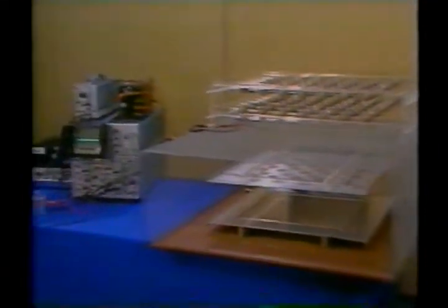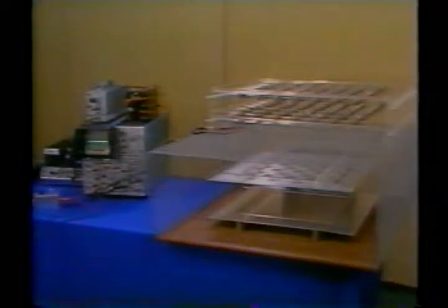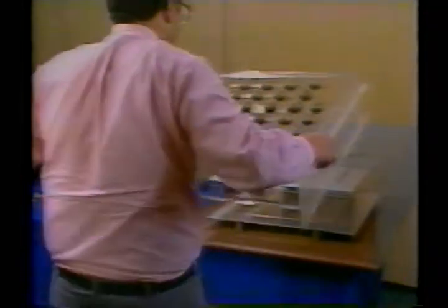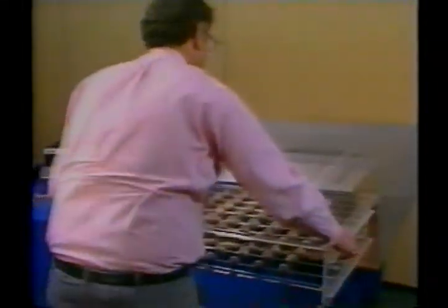Here's the top plate connected to one side of a differential amplifier. Because the spacing between spheres is more than 2 diameters, the increase in capacitance caused by the spheres is small. To measure the small change in capacitance that results from inserting the array, the parallel plate capacitor is in one leg of a bridge.